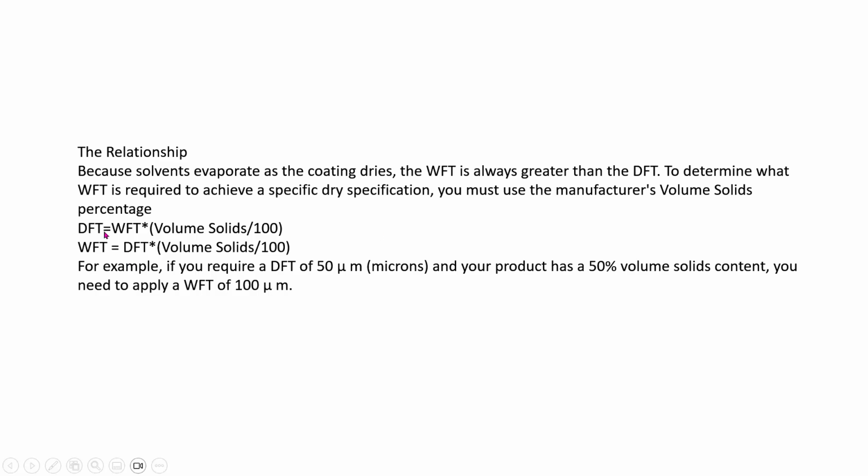Dry film thickness is equal to wet film thickness, WFT, into volume solids divided by 100.